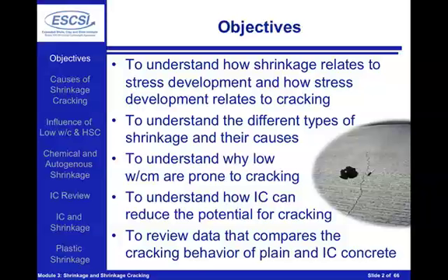We want to understand a little bit about why lower water to cement ratio concretes may be prone to cracking. We're going to talk a little bit about how internal curing can help to reduce the potential for cracking. Then finally, we're going to review some data that compares the cracking behavior of plain and internally cured concretes. So with these objectives in mind, let's begin.